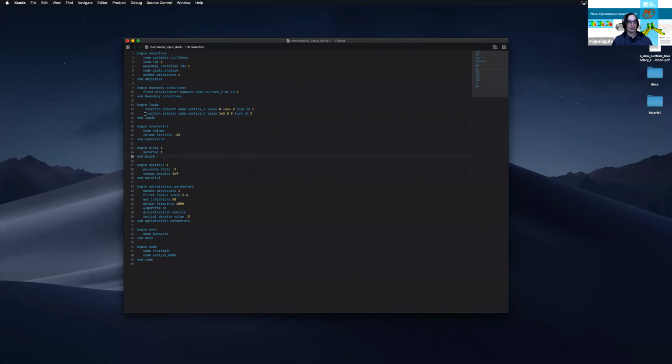So yeah, basically you could have another load, and then you assign that load here. And what Plato is going to do, when it does the optimization problem, is run multiple executables simultaneously, for both load cases. It's going to compute the objective value for load case 1, and also the objective value for load case 2, and add them together into one value. That will be the objective function value for the optimization problem, and it will keep going.